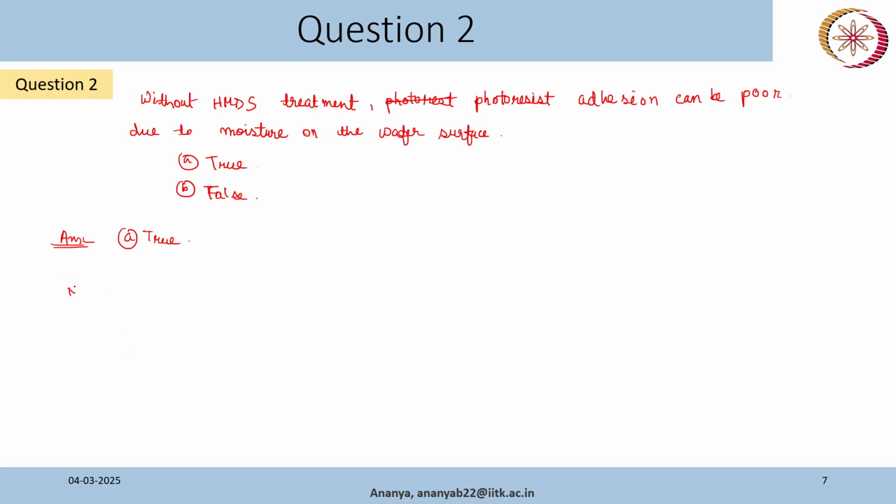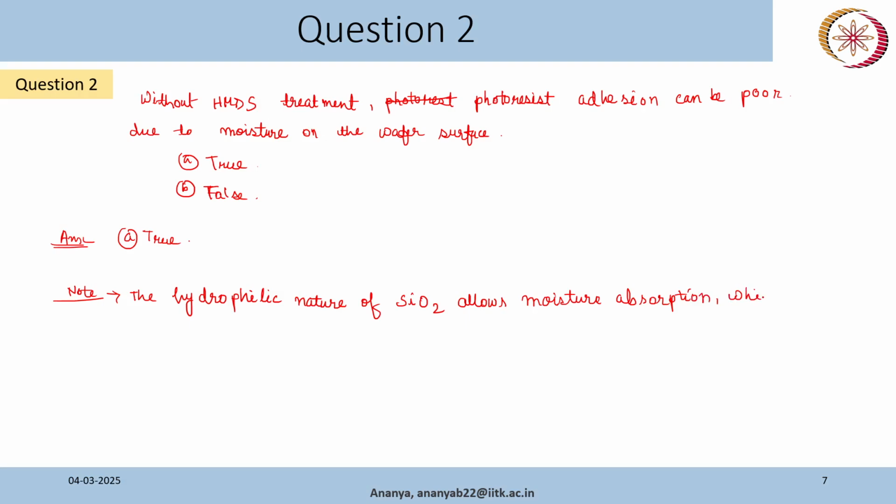I will write a note here. The hydrophilic nature of SiO2 allows moisture absorption, which leads to poor adhesion of photoresist.